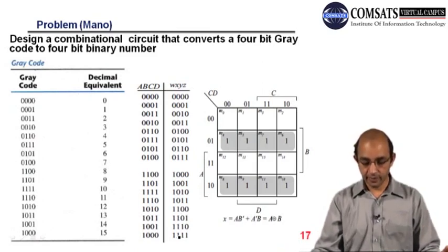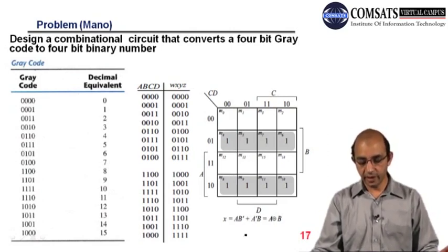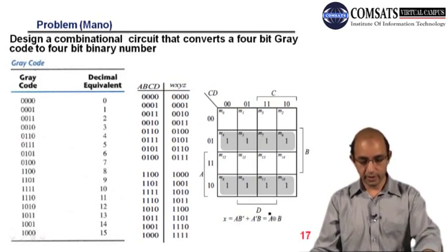So we have the rest of the bits high. You can see that we have this grouping in a row, and then we have this grouping again at the bottom row. So we are left with A bar B, A bar B, and AB bar. So this is the XOR operation. This is for X.